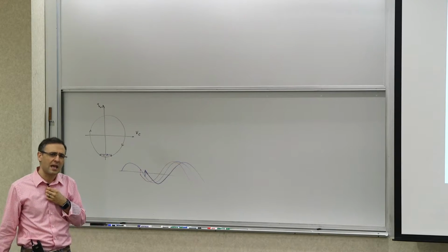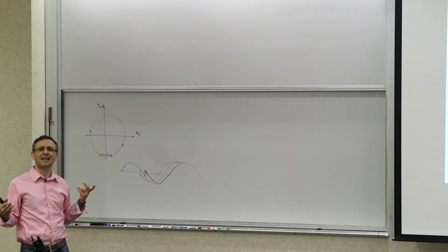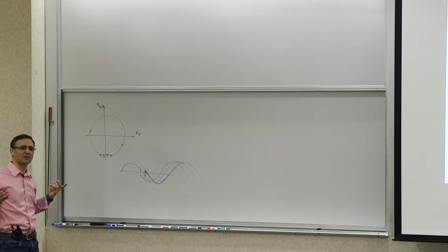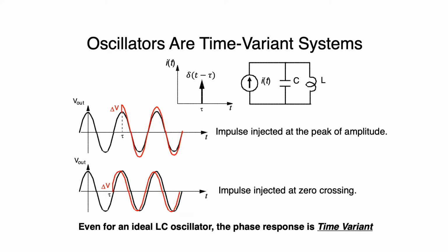And you may come back and say, wait a second, how is that possible? How is the energy of the oscillator not changing at all? Because I'm injecting current into it, right? Well, injecting current is not necessarily equivalent to injection of energy. The power is determined by the product of the voltage and the current. The delivered power P is V times I.